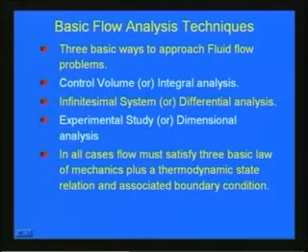The third important approach of fluid analysis is called the experimental study or the dimensional analysis. In the experimental study, we try to replicate the real problem in the laboratory on a smaller scale and observe what is happening, and then with dimensional analysis or various other analyses, we try to solve the problem. So, these are the three important analysis techniques used in fluid mechanics: the integral analysis, the differential analysis, and the dimensional analysis or experimental studies.